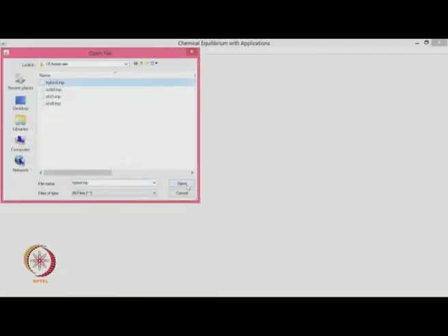Anyway, we will go to liquid hybrid propellants. Now, hybrid propellants, as I said, we can look at HTPB binder and liquid oxygen as oxidizer. That is what we have selected here, liquid oxygen 100%, HTPB binder 100%.